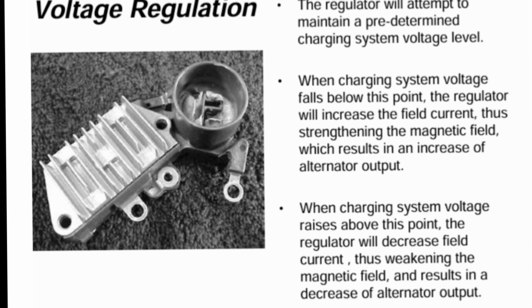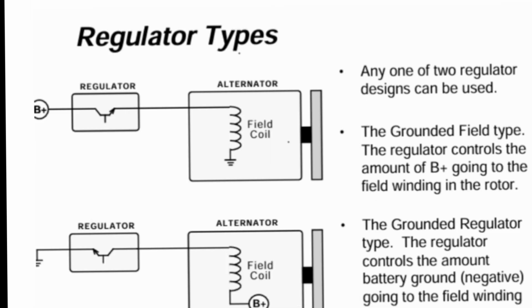Rectifier contains diodes. Use diode mode in multimeter. Check forward bias, reverse bias. If diode conducts both sides, diode faulty. Faulty rectifier causes low charging, battery drain, AC ripple.